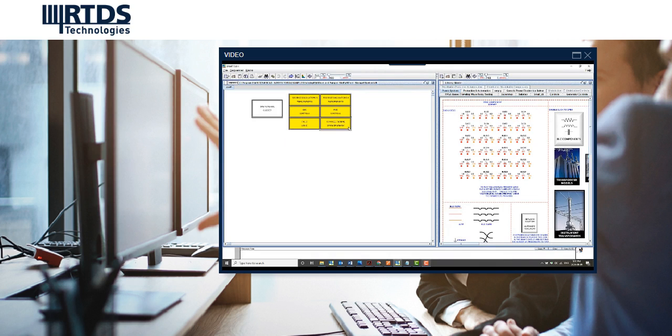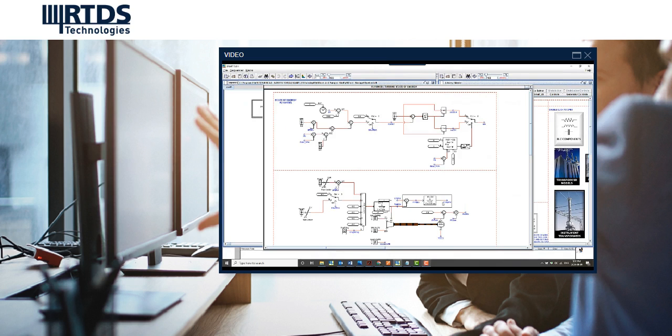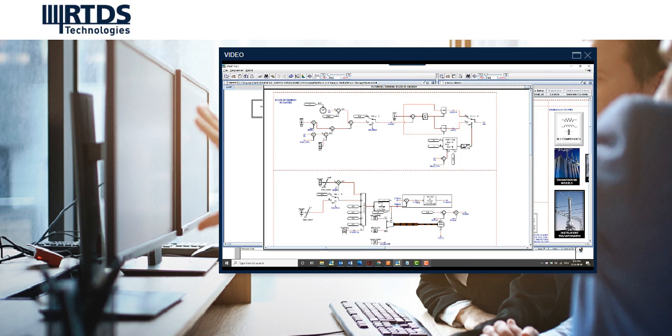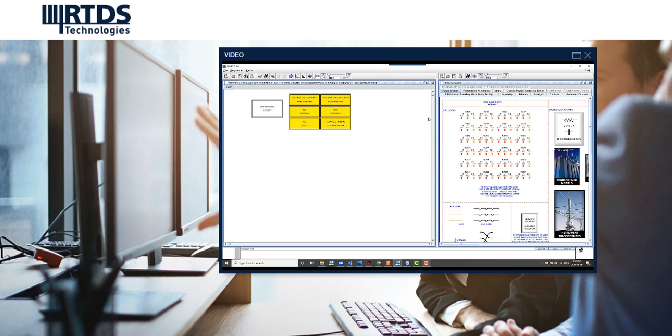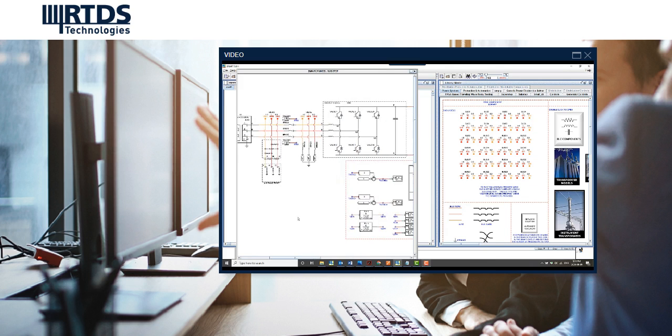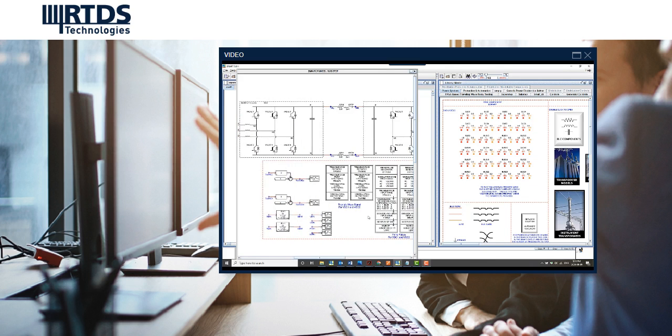So the flywheel is basically modeled as an additional mass on the rotor of our PMSM, permanent magnet synchronous machine model. So here we have our multi-mass model, and we're calculating the state of energy for the flywheel turbine. And then we have our converter that's interfacing the flywheel with the grid. And this whole case is simulated in the sub-step environment at a relatively small simulation time step.